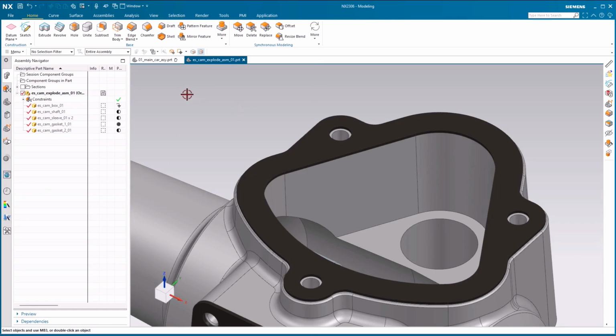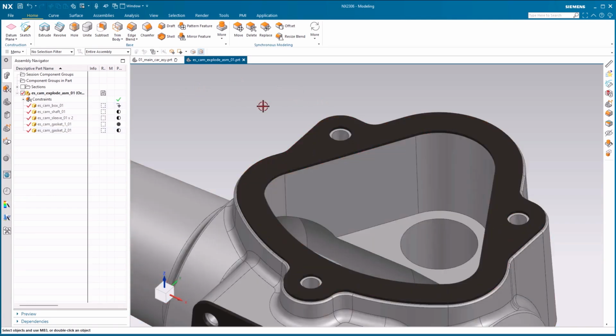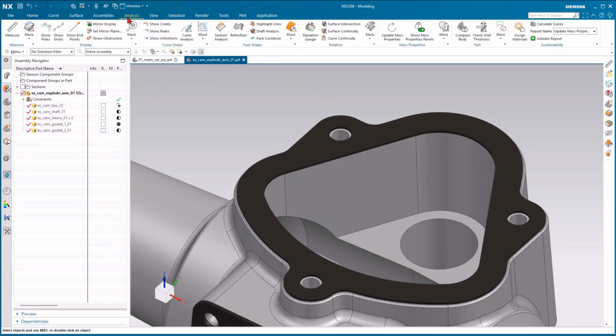So the first technique we'll look at here is the ad hoc method of creating a requirement on this part and then checking the validation on that to make sure it falls within the requirement guidelines. So I'm going to go up here and create a measurement. I'm going to go up to the analysis tool here, go into the measure tool,